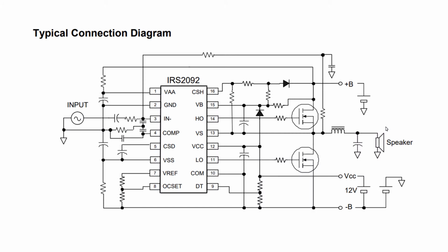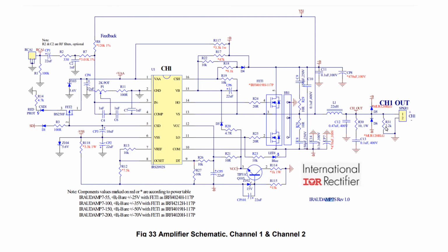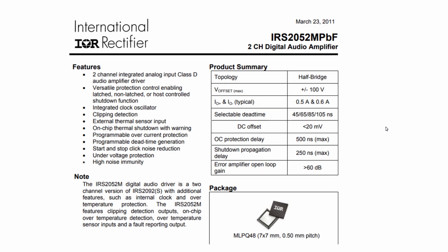This chipset requires 12 volts stabilized additional supply voltage. There you can see real working design schematics, well known as IRAUDAMP7S. I would say the design is relatively simple, and with good selection of electronic components you can make an amazing performance amplifier. Two-channel version with some extra functionalities like thermal protection circuits and synchronization pin for bridged connection. I guess that this particular gate driver has been used in famous ICEpower 125A6 too.